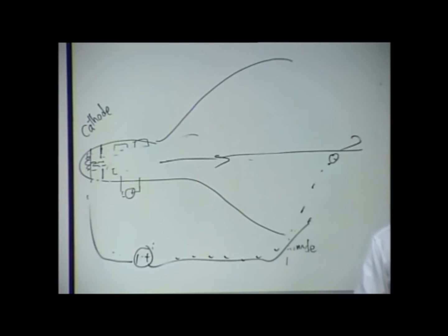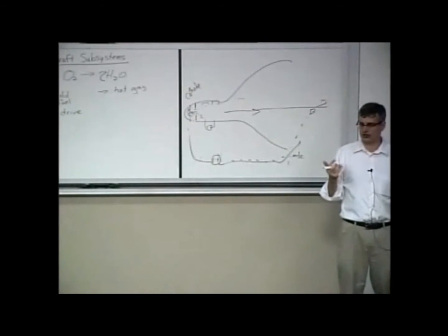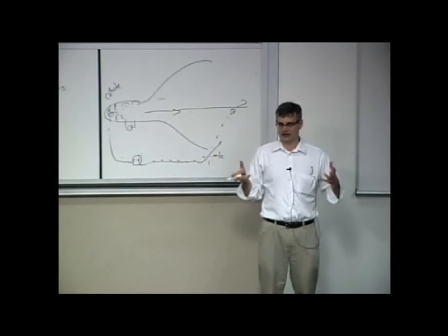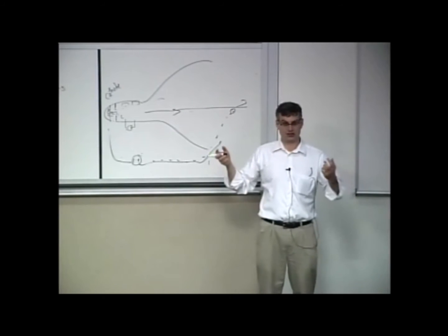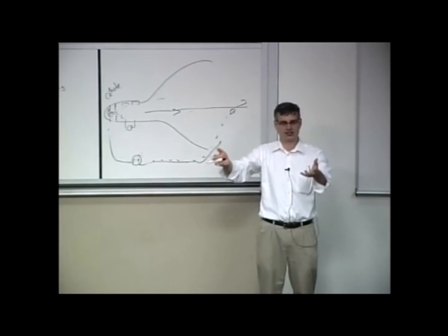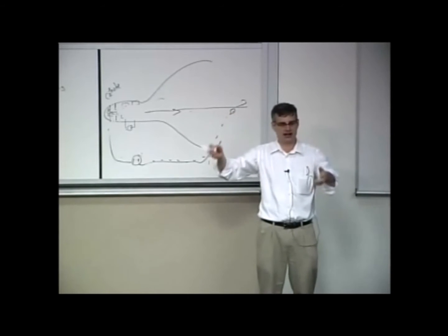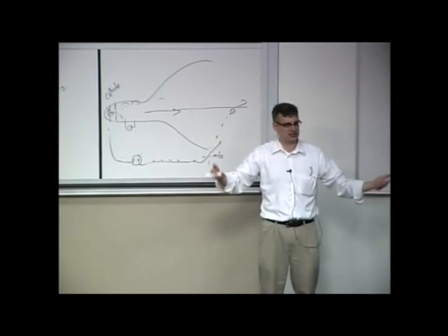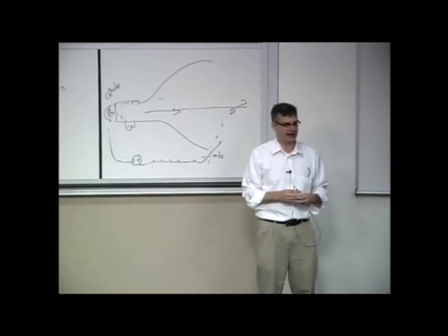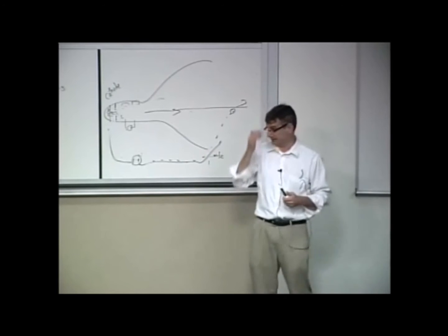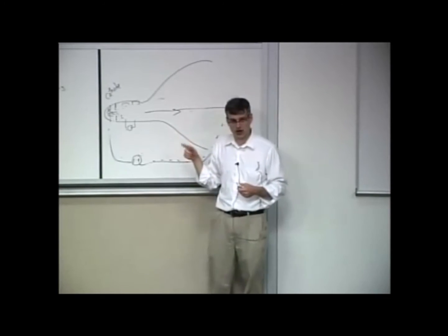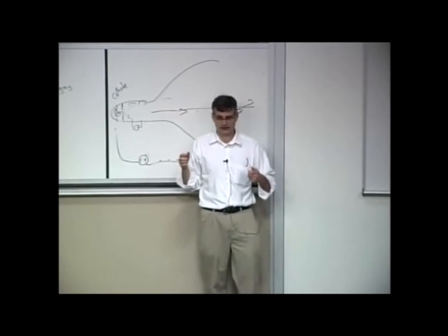And of course, you do that because if you didn't have that circuit closure, you'd have this negative charge building up on your spacecraft, and eventually it would electrostatically attract all of those positive ions that you were throwing out the back, and you would slowly lose thrust and effectiveness in your ion drive. Now, what's the nice thing about this? Why do we use this? Why is this an alternative? Here's the problem.